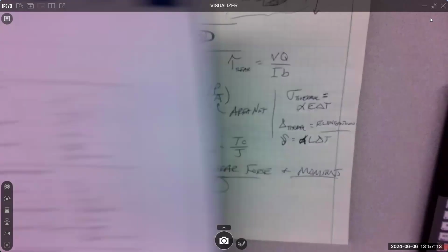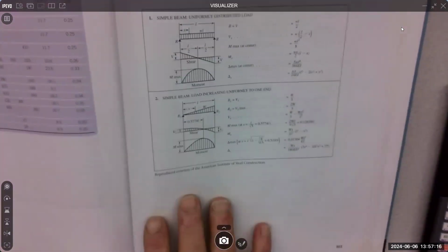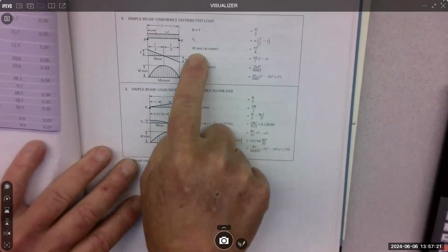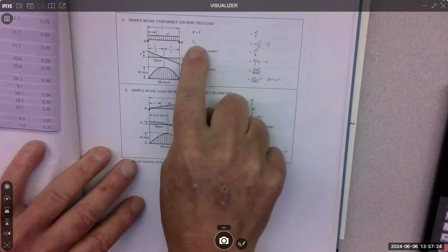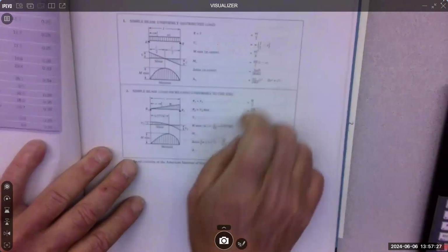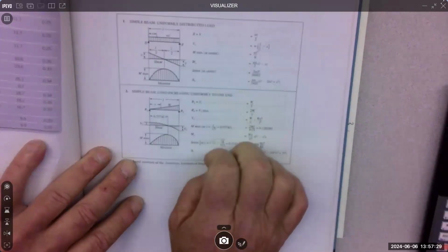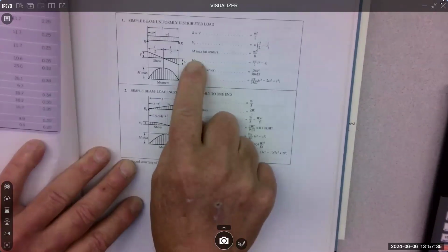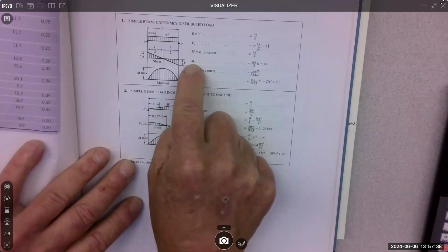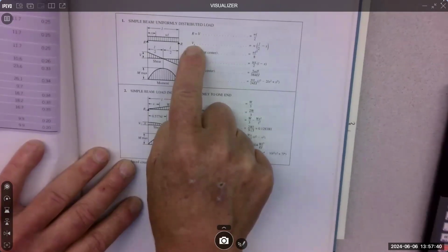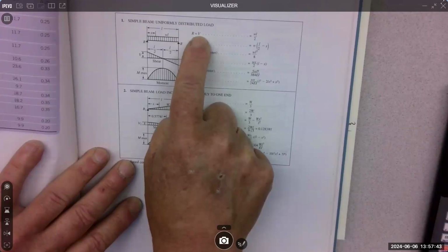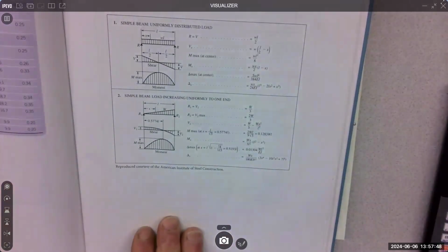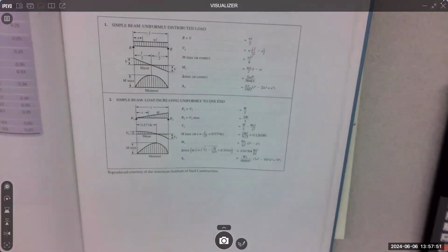But these formulas in the back, they have the maximum moment right there, formula, and they have shear at any location. This does not have shear max. So it's not just deflection that's back here. It's max moment, it's moment at any location, it's shear at any location. It's telling you that R equals V. These resultants equal shear. So there's a lot of information there. But that's only if you can match it perfectly.